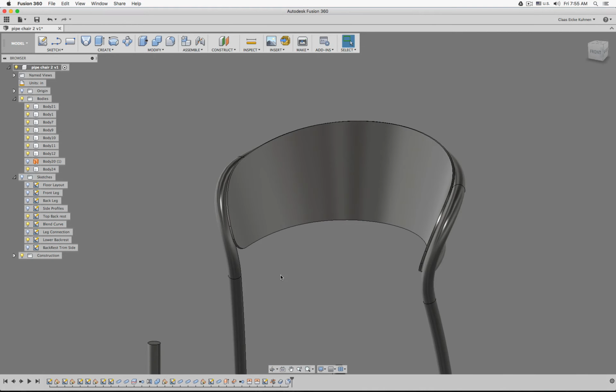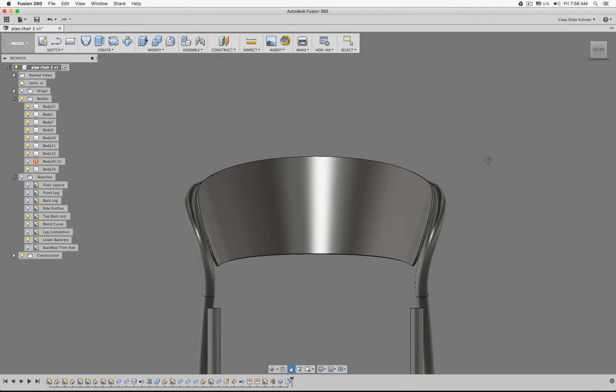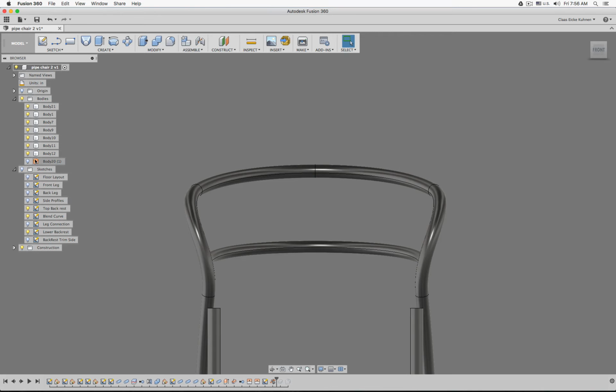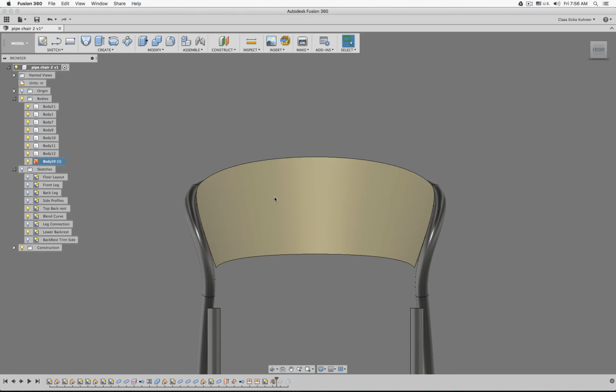Good. Let's say we would like to have something cut out, maybe a slot or two holes. So we could, for example, do this from the front. But I will actually go back to here first, where I have the surface, because I can also just do these whole cuts right into my surface, and then I thicken the trimmed surface.